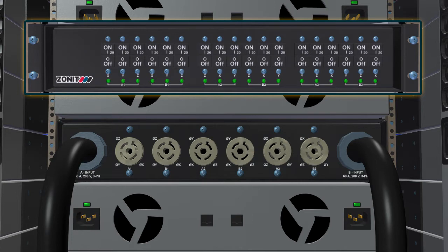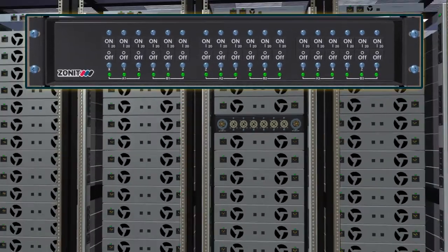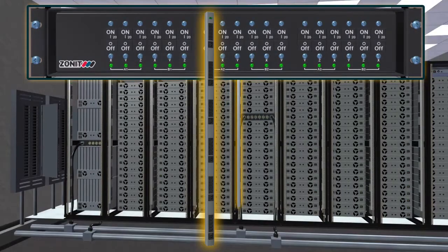Due to the Z-PDS unit's different location in the power topology from a power whip or a busway tap box, the 3 circuit breakers do not have to be pinned to trip together, which is the case for the circuit breakers protecting a power whip or a busway tap box receptacle per the National Electrical Code. This means that if a multi-phase plug strip or other load is plugged into a Z-PDS unit and one phase is overloaded, only that phase will trip and the domain of failure is minimized.